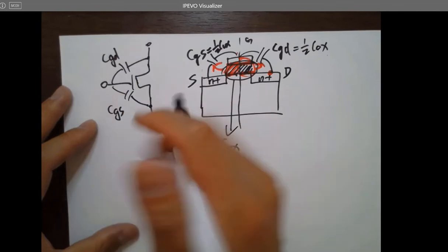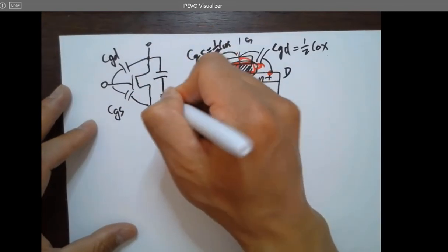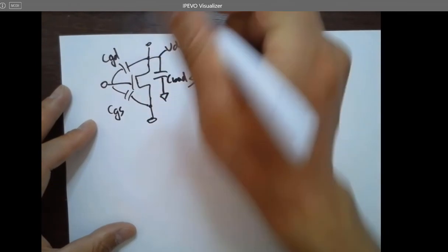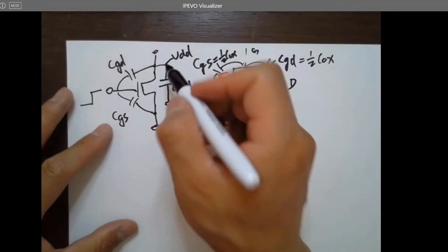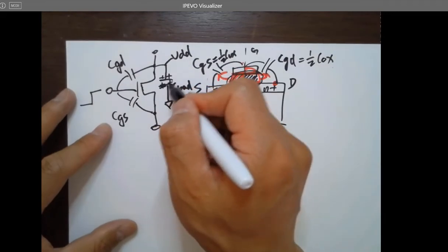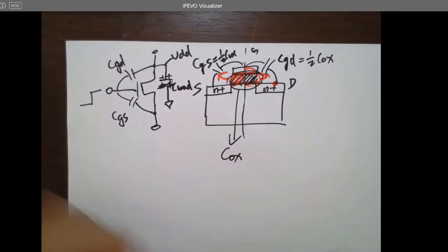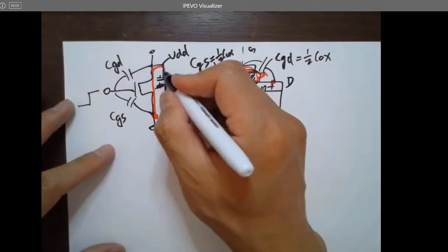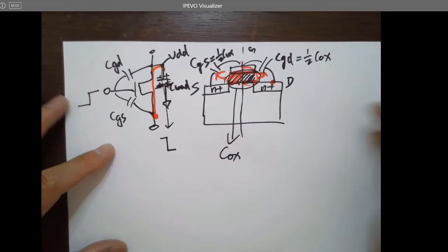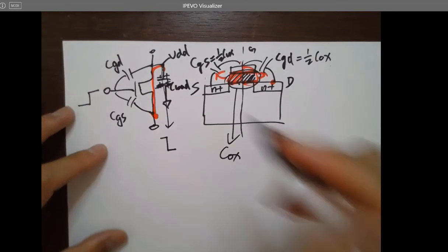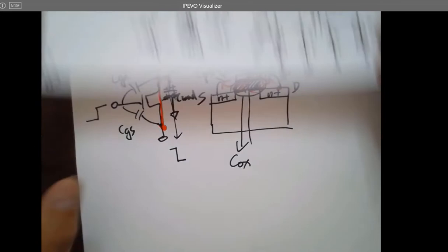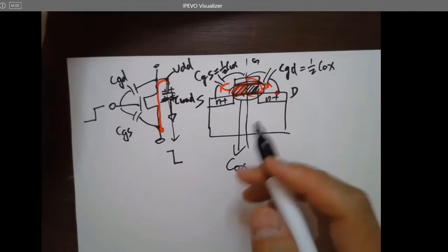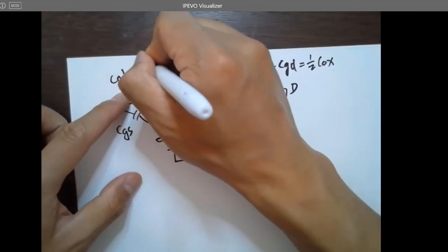And if we look at this circuit again, if we have a capacitor as a C load, which is initially charged to VDD, whenever this is switched on, all these charges previously stored in the plate, negative charges on the other side, will be discharged through the channel and go to the ground. So the voltage at this output will be switched off. These two nodes are doing the same job as this circuit, which means the effective capacitance over here, physically, I understand this is CGD.